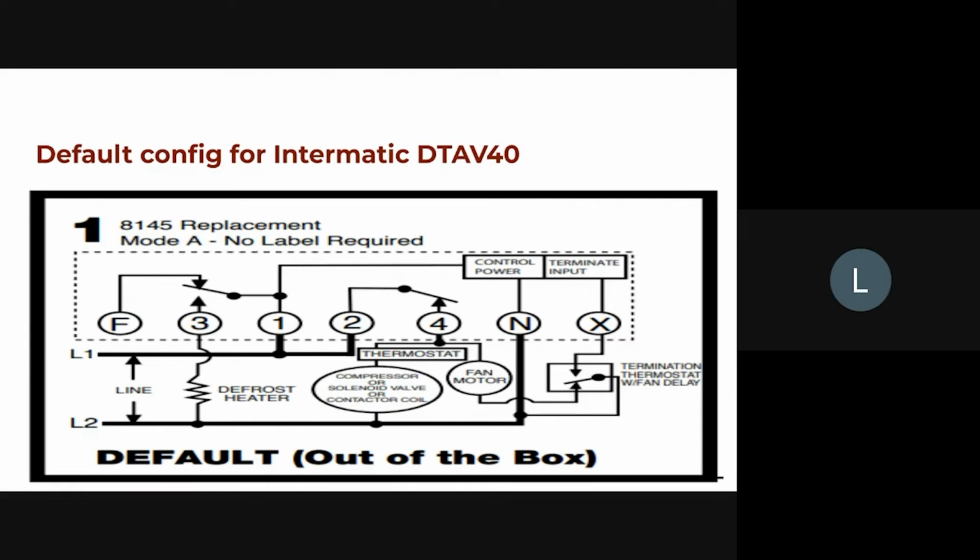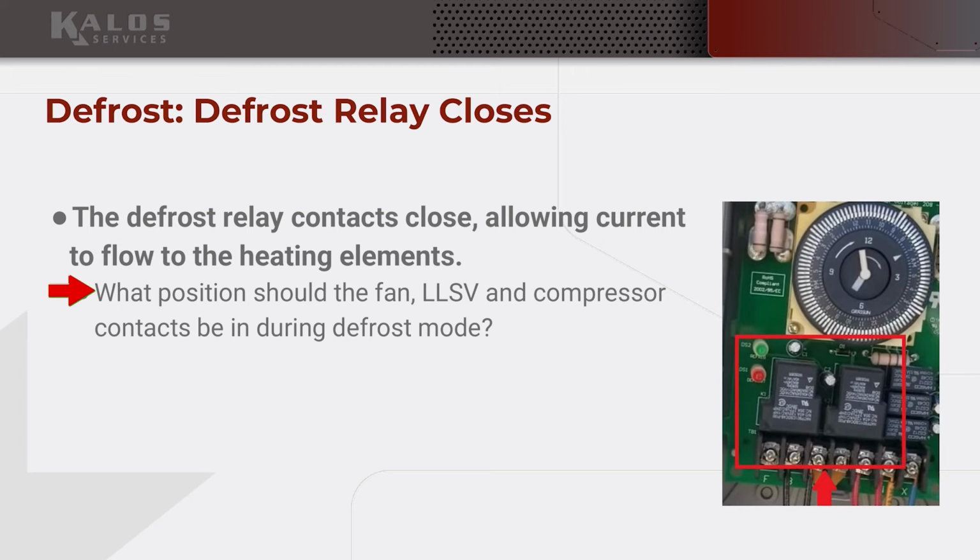Okay, yes, let's back up a minute. That previous question you had on that slide was asking what's going to happen to the liquid line solenoid, fans and compressor. There it is. Okay, so basically what that's going to do is turn all of those off, even though the power supply may be different.